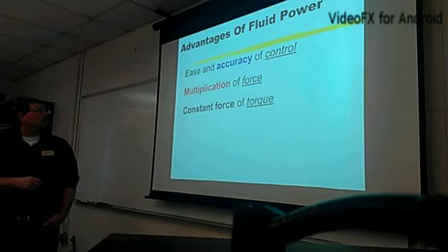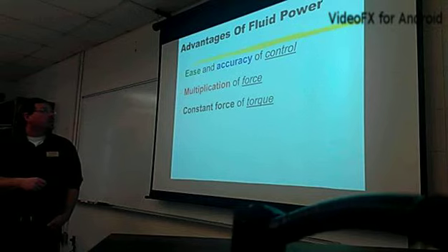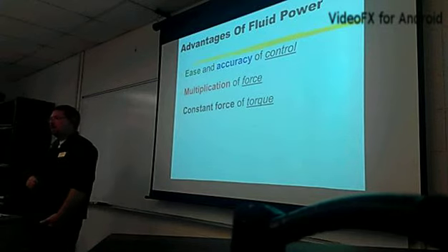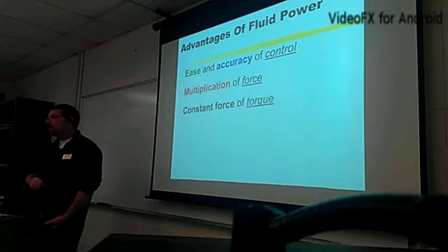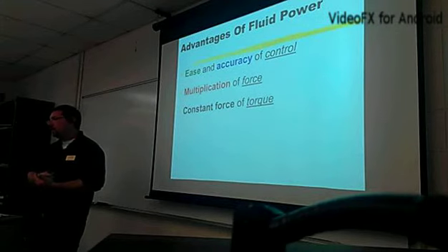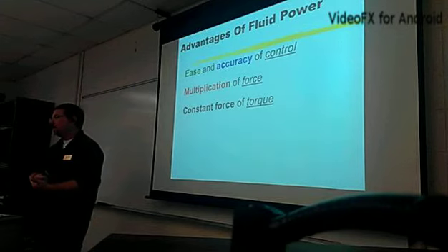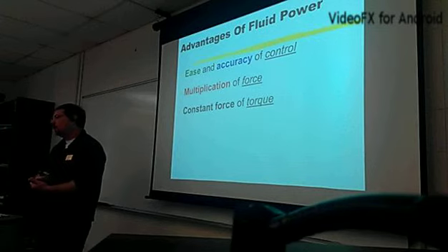Constant force or torque. What that means is, using fluid power, if you need to have a clamp or a press or a mold operation using hydraulics, if you need to hold pressure on something, that's much better than, say, mechanical, where there's slippage in the gears. Electrical, there's slippage in the EM force of the motor, okay, unless you have some kind of positive traction planetary gearbox, there's going to be some kind of slippage on an electric motor, so you don't always apply that constant torque.